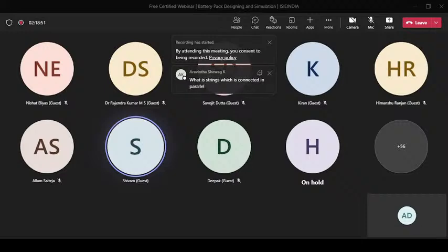For the questions on active and passive balancing: whenever a pack is built, there are hundreds of cells connected in parallel combinations. Whenever energy is drawn from a cell in a battery pack, it is not compulsory that each and every cell will get equally discharged. Why does it happen?